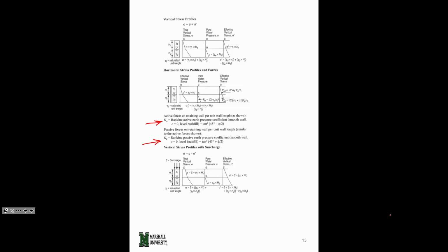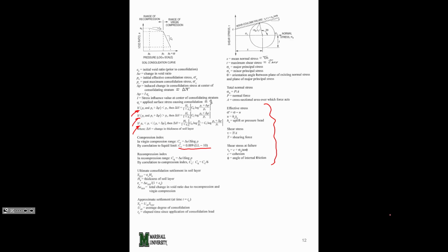Seen a lot of problems where they have the sliding block, slope failure analysis here. It's pretty straightforward if you just stop and think about it and get all your values. It's kind of odd over here. Back up 2 sheets. Here in this equation right here, they go tau sub F equals C plus sigma n tan phi. But when we come back over here, they've got this tau sub FF. That's the same thing. That's the same thing. They've got their symbology a little different there.